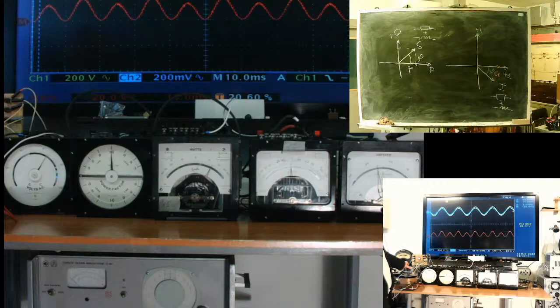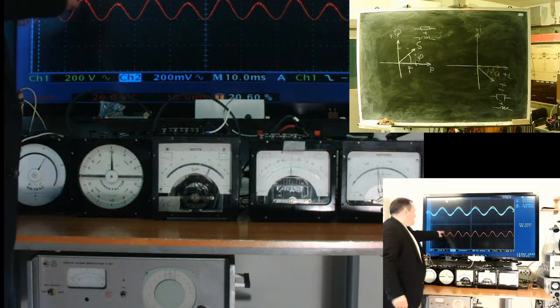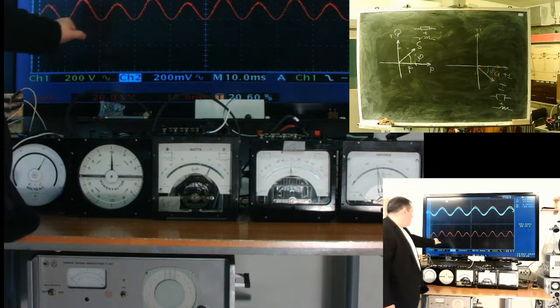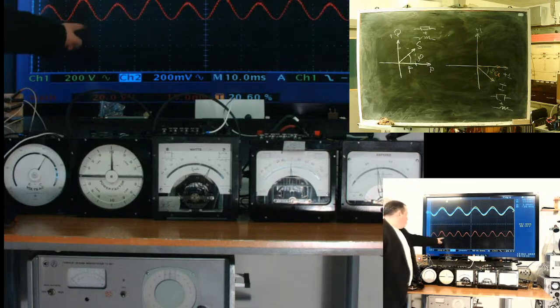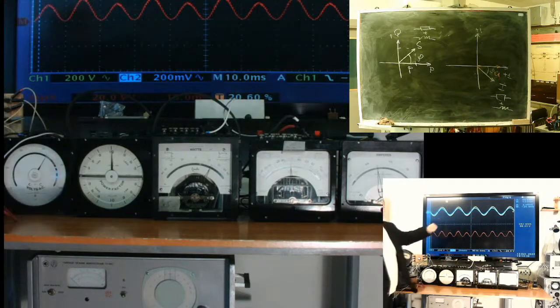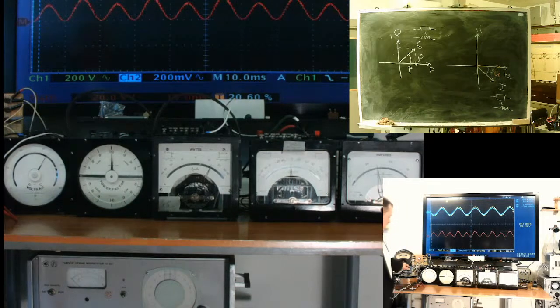Let's take a look at the red line. Cosine phi or power factor 1, angular shift 0. You can see the instant power. This red line is the instant power. And to get the power, we should integrate; one division is 10 milliseconds. So from this point to this, we need to integrate and we will get active power. You can see it's positive.